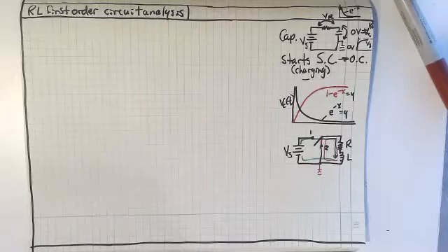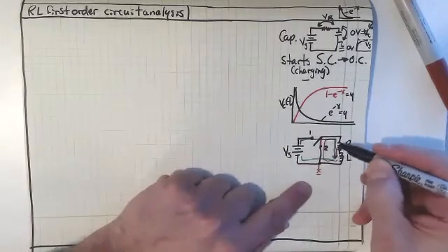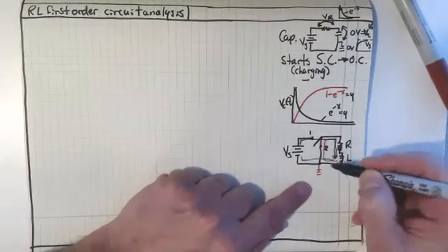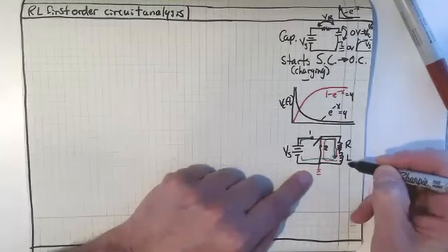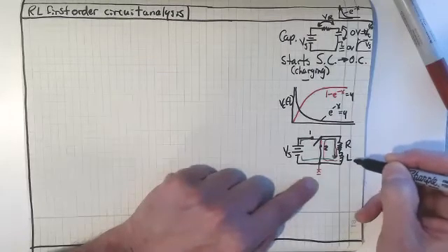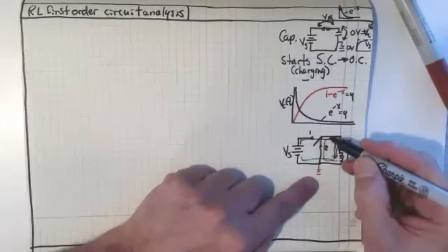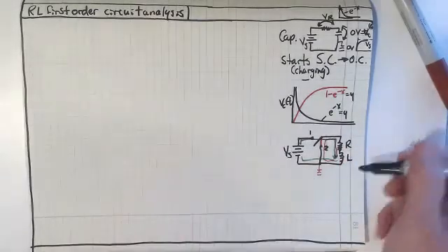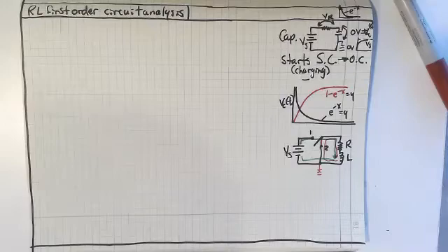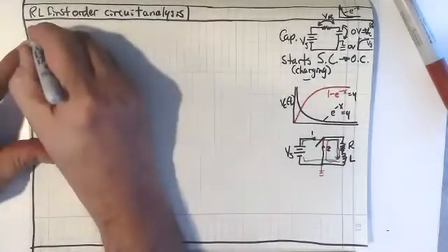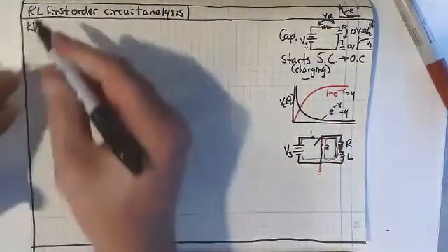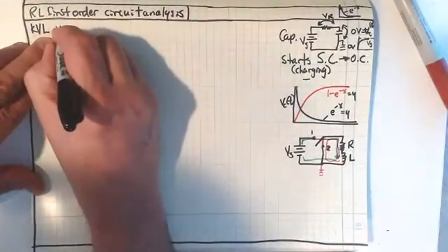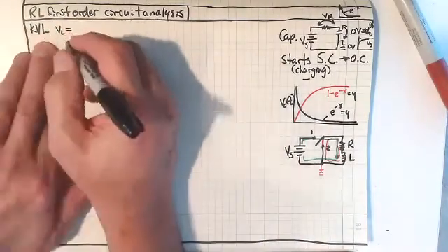When we're discharging that inductor, what are we really doing? Let's look at this circuit now, just the red circuit right here. I'm going around in a circuit, right? So if I'm going around the circuit and discharging the inductor, and that's going through the resistor and continually going around, what do I have there as far as the KVL goes?